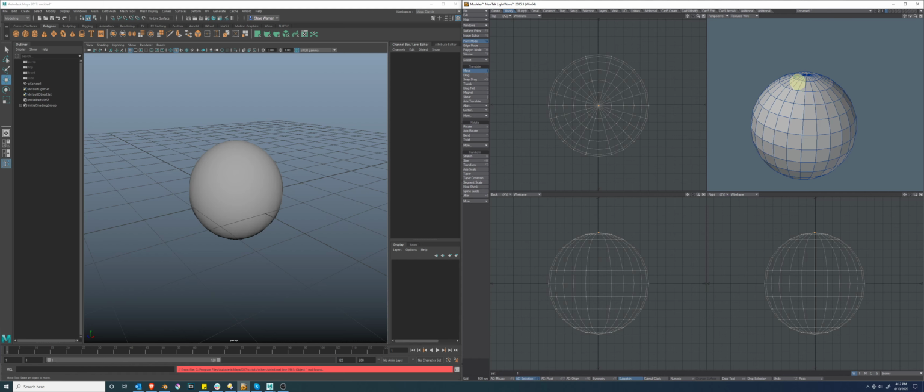But there's a way for us to utilize a tool that not only moves that one vertice, but moves vertices all the way around it with a lessening degree of influence. And in Lightwave, that's called Falloff. So if we use a tool called Dragnet, and you see here that I click and drag, you can see now that I'm impacting that top vertice, but going down the rest of the geometry, lesser and lesser, is having a less impact or less influence all the way down the geometry.